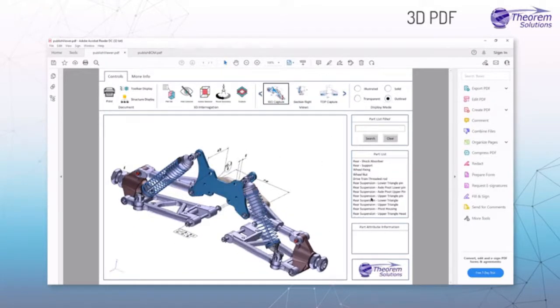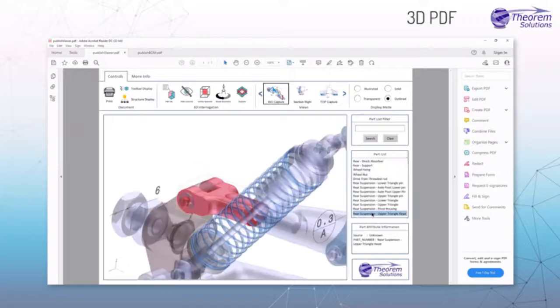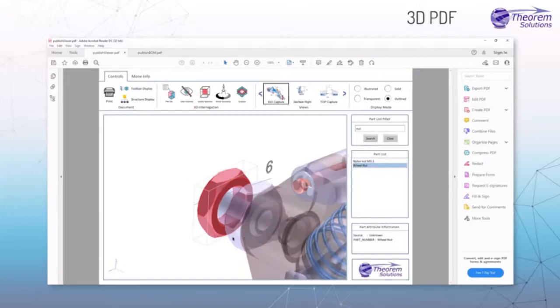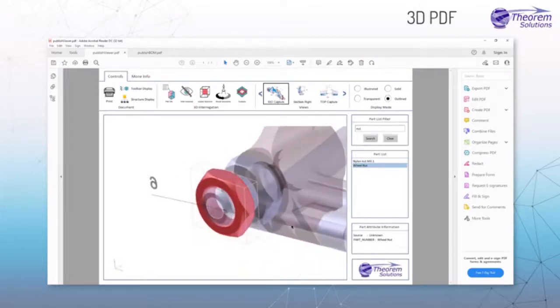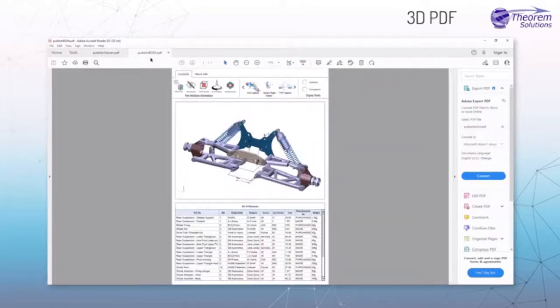And finally, we've got a part list here. You can reference the individual part list and show relevant attributes when you select a part. So if you want to see material, finish, and creator, when you select a component, you can do that. Similarly, you can search the part list: if you've got a part number and you want to find that part in the geometry, you can do that directly from the search capability. And again, this is just a different layout.